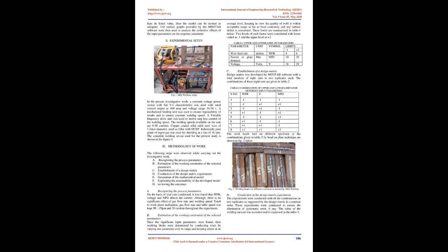Now, in order to calibrate a power source, a mathematical relation is required to be established between these parameters. It is of significance, as otherwise there is a possibility of making erroneous inferences about a process. This study is done to calibrate a flat VI characteristic power source by developing an analytical model between the process parameters and the response parameter, which is welding current. To conduct the experiments in a structured way, so as to reach a logically reliable conclusion, it was felt to use some technique of experimental design. Many options are available for the purpose, like factorial design and Taguchi method. After referring to a number of literature works, it was concluded that Taguchi's approach would be appropriate as the number of experiments included are less and the L8 model would suit the present investigative work.